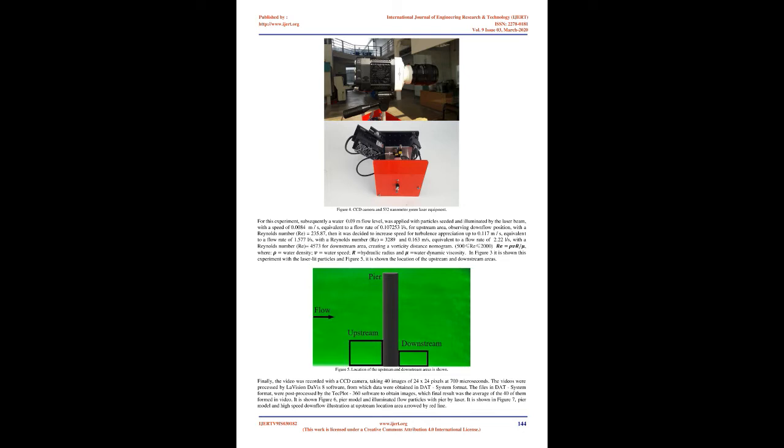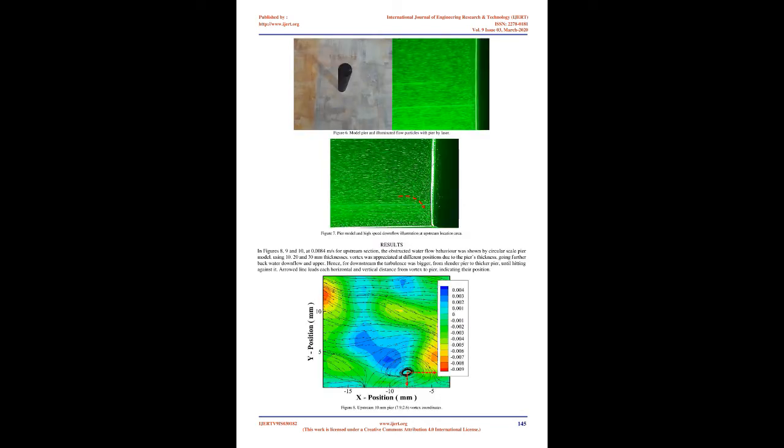These same studies are used to verify the structural quality of the bridge using vibration methods 4, which is expected to improve the available deterministic, stochastic or empirical mathematical models. It is hoped the combination of many studies will lead to laboratory results that are more attached to the real system, and that numerical models, whether simple or very complex, that are used to characterize sediment erosion, offer better understanding of scour in the future. 12. With this, scour problems in the pier of a bridge such as shown in Figure 2, could be foreseen coming from the original design, or resolved after being evidenced in existing infrastructure.